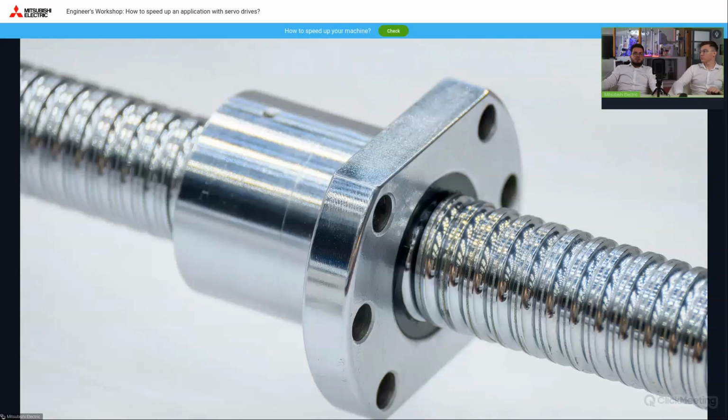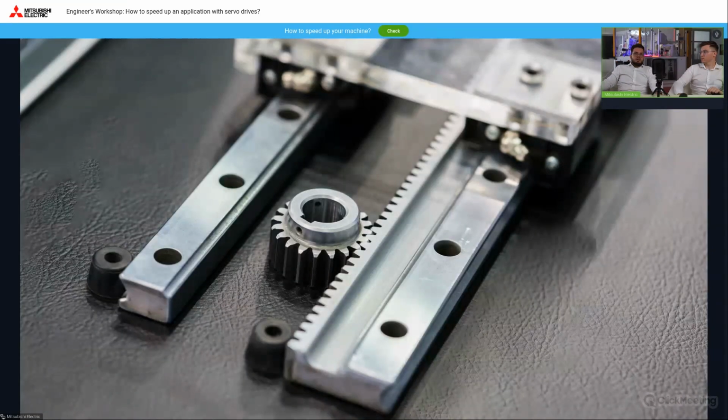Still, we have to remember that the larger the screw pitch is, the greater the maximum possible speed. Maximum permissible speed and acceleration value of the screw also have their own limits. Another possibility are rack and pinion systems, which have similar speed characteristics to belts, but with much higher forces and achievable precision bigger than even screws.